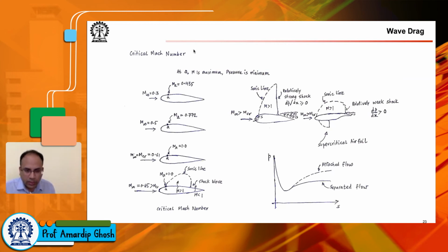On the other hand, if you are looking at a subsonic case, the moment you see an airfoil wing cross section such as this, you can think of it as primarily a subsonic vehicle wing. And if you see the wing is thin, then the wing has some special design. For example, this one is a subsonic wing, but it is known as a subcritical wing. There are reasons why we design these wings, but nonetheless, just from the look of a wing, you can guess whether it is for a supersonic or subsonic flight vehicle, for low speed subsonic or high speed subsonic, and that will be evident from the discussions that follow.